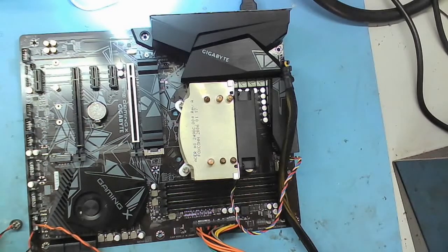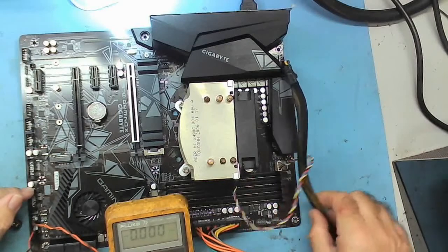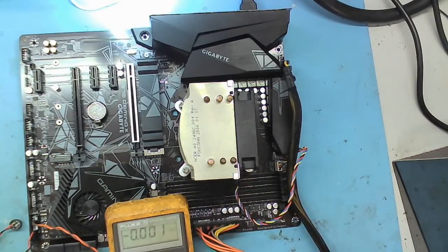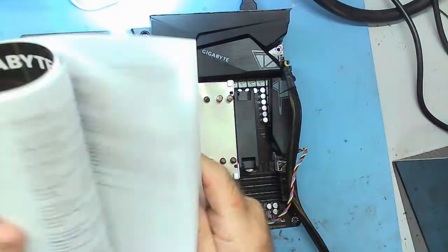And this is how that CPU socket looks like it's broken. Maybe there's a problem. That powers up, but nothing seems to happen. It doesn't beep. Well, let's stick some RAM in it. I can't imagine this will work if it doesn't beep without any RAM. Do we have a manual with this one? Yeah, we do, so see which way the RAM goes. The fact this doesn't beep without any RAM tells me this isn't actually booting up, it's just powering up.